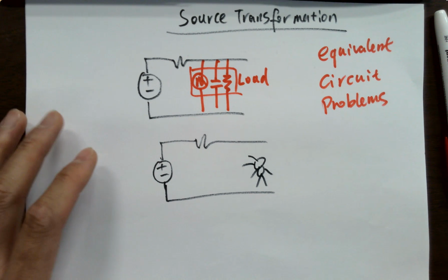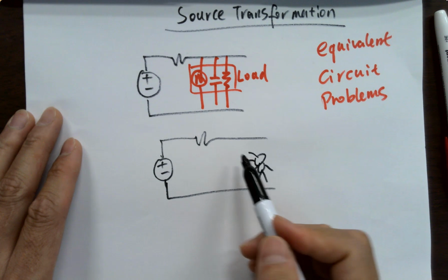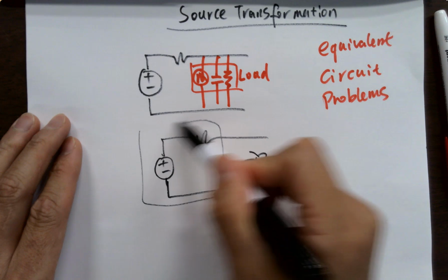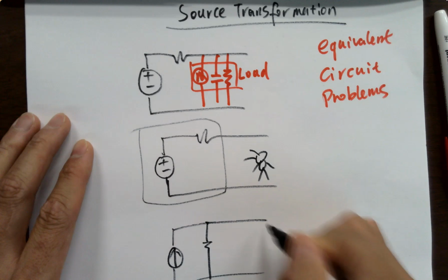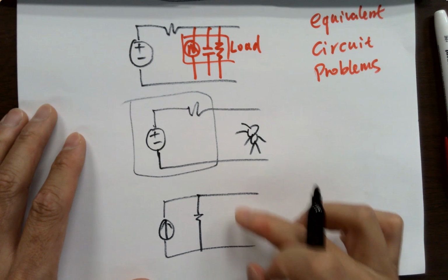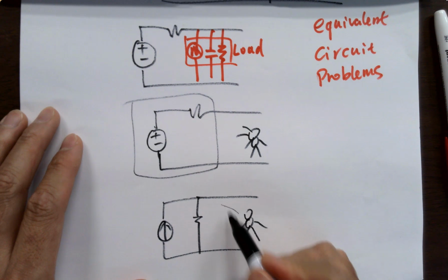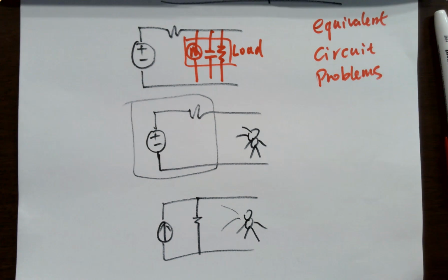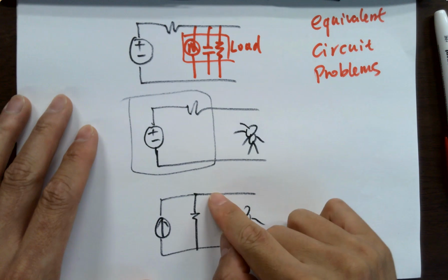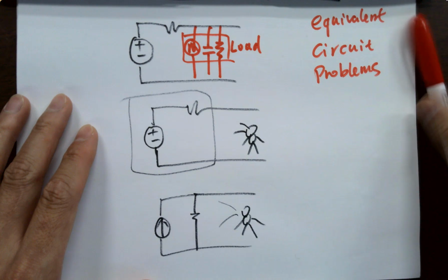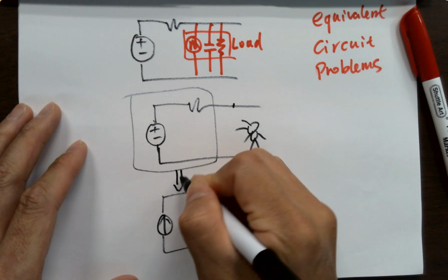That's what's happening, right? So if you're looking at the circuit from right to left, this part of the circuit can be converted to a current source and a resistor in parallel, with the open circuit here as well. So you remove the load, right? You're looking at the circuit to see what it is going to do to you. Doesn't matter what the load is, right? This circuit is going to deliver a certain voltage at this point. Okay? So you can convert it to this.